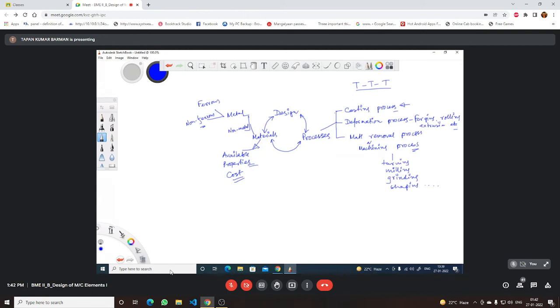Now when you are trying to remove the material of this cast component, then basically you are removing the stronger part of the component. So for casting operations, we always try to minimize the machining operation to make the final product. Understand? This way, we have to consider these parameters at the design stage. That is called manufacturing aspects in design.